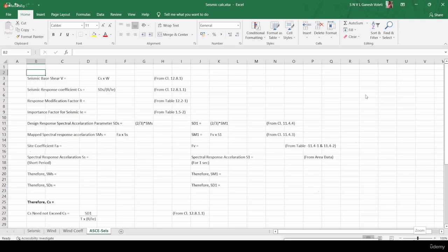But only the load combinations and the design, where we have to check the code option, will be done by ASCE 7 only, because it allows web tapered members also. The loads and analysis will be done as per the Indian codes, and design will be done as per load combinations of ASCE.